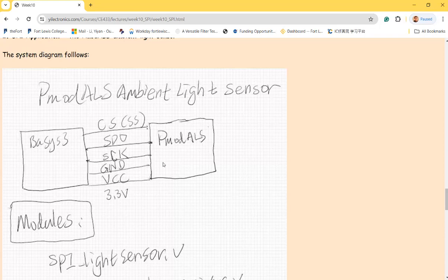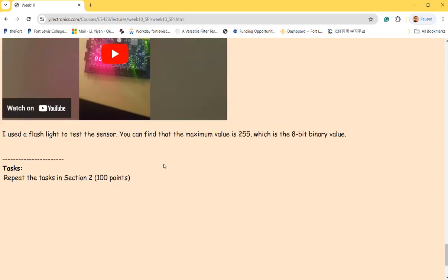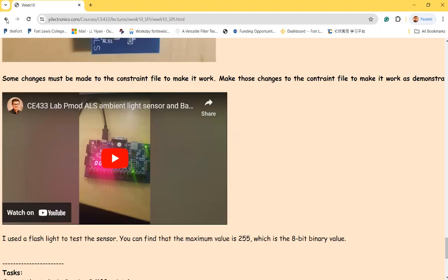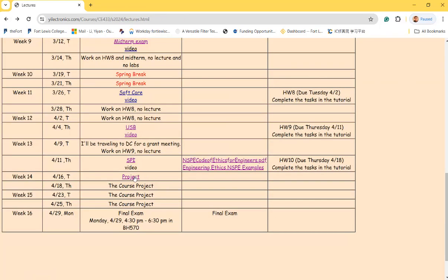Okay, so this is the light sensor. I have it here, so everyone will grab one. The light sensor is on a little PCB and it has a standard SPI connector on it. It's 3-volt logic, so you can directly use it with an FPGA board. We never had any big problems with this example. It's pretty simple.